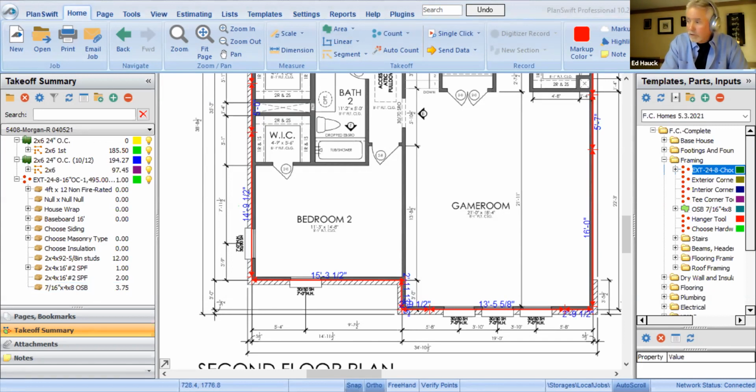What Dave's talking about here is controlling the estimate. He just talked about picking up 40 studs on a small house just on corners. And by the way, there's no added value to a buyer because of how you frame a corner. So a lot of this is you have to control your estimate, control the design, and then teach your team and your framers how to do what Dave just described.